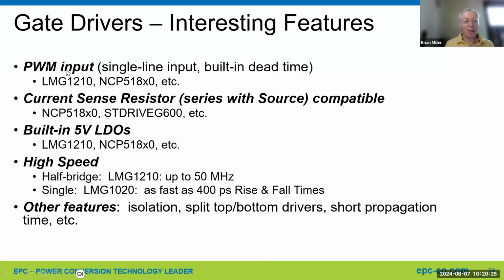Some have a PWM input, a single line input. Some of these you can either put two lines in, like for top FET and bottom FET, or just one line, and the gate driver itself can control the dead time. You can have very small dead time with GaN FETs, and some of these gate drivers can actually help control that to optimize the performance.